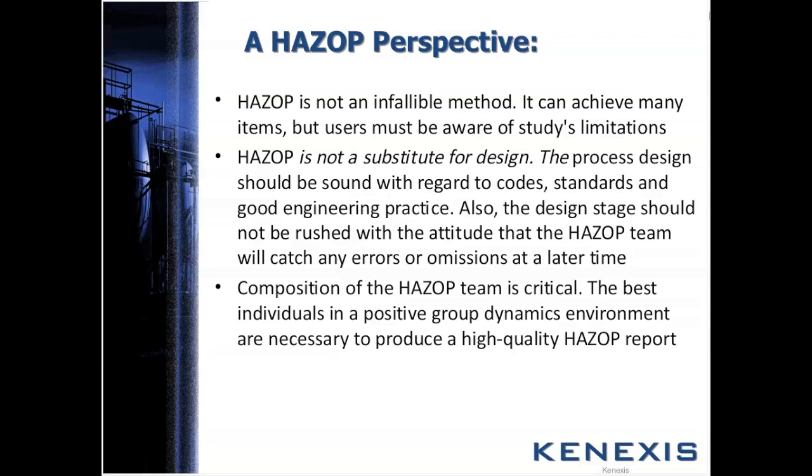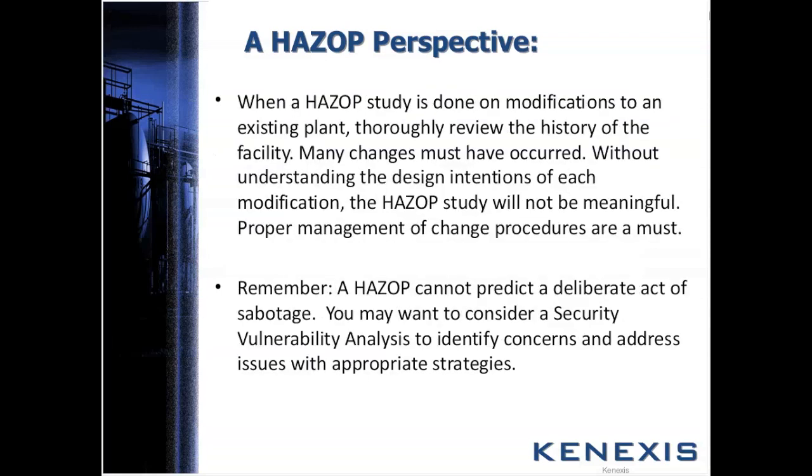HAZOP team is very critical. When you look at modifications on the existing plant, you have to very, very extensively study the management of change that's been done so that you can understand the changes and reach a proper study based on the potential new hazards that might be introduced. And the HAZOP can't predict deliberate acts of sabotage. So if you've got that kind of an issue, you really should consider doing a security vulnerability analysis to identify the concerns and address the issues with appropriate strategies that are outside the venue of a HAZOP.